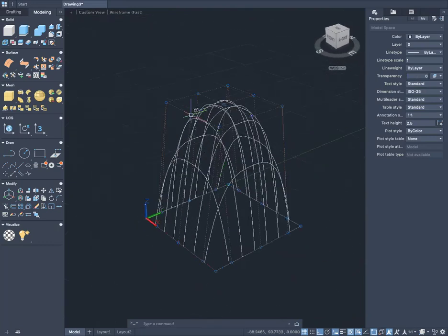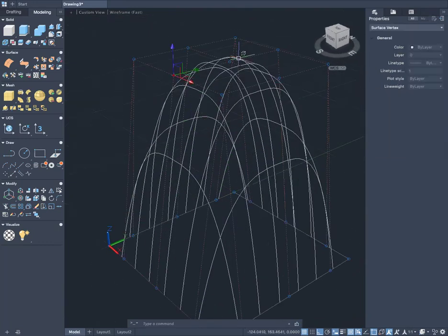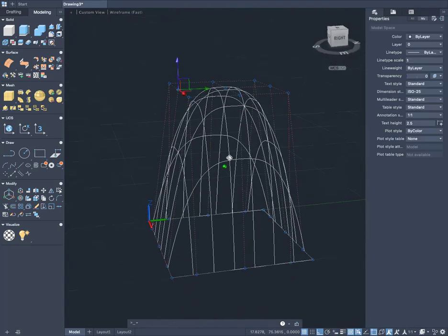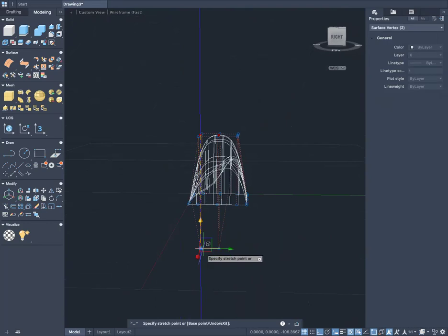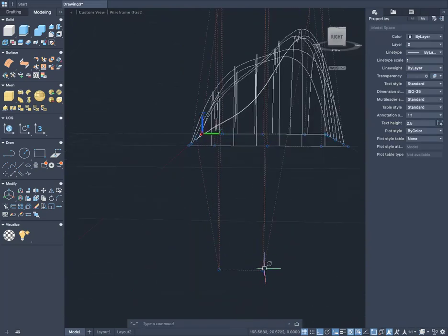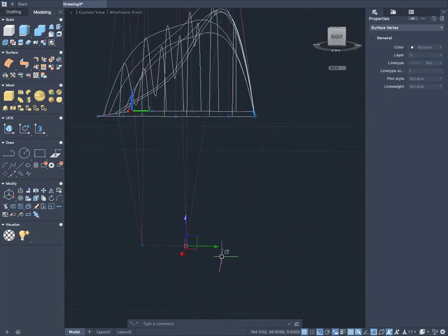I'm going to rotate slightly and go back to selecting these two points. I'm going to grab the blue cone, bring my line down, press escape, and press the back blue. I'm then going to select the back point that we've brought down, this vertex here.